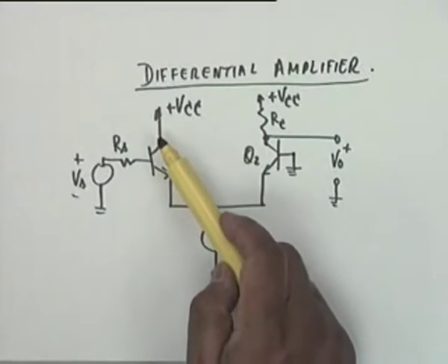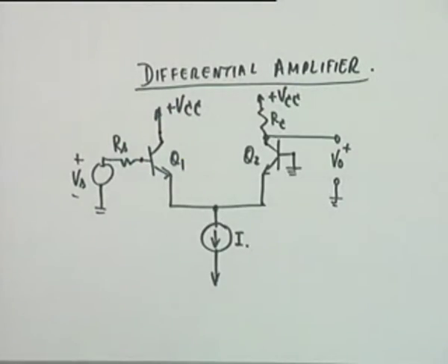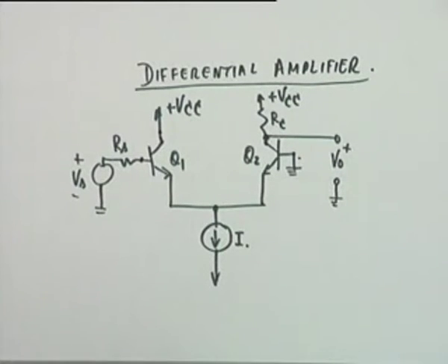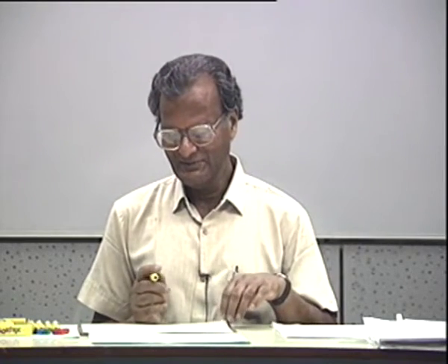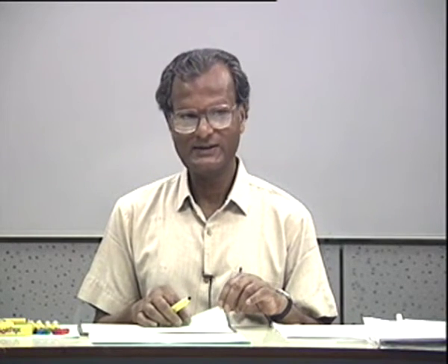Why is it wideband? It is wideband because this is a common collector, and therefore C mu from here to here does not cause Miller multiplication. Similarly, here from here to ground, once again it is grounded. So both C mu's, their teeth have been taken off, so they can't bite. Okay, they can't harm this circuit. Now let's see the analysis of this. It also gives very elegant results. Analysis can be done in a very simple manner.